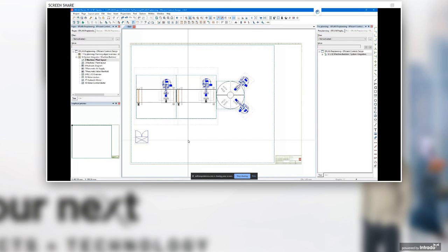And now at the same time as I've done this graphical layout, you can see that my system has conveyor system 2, conveyor system 3, it has my turntable. And the more I drill down, if I look at my conveyor system 2, now I've got a cylinder, which is the cylinder that actuates these two clamps. I've got a sensor at the beginning of the conveyor. I've got a sensor, a light barrier at the end. I've got the motor that makes the conveyor system run. And I've got my robot right here.